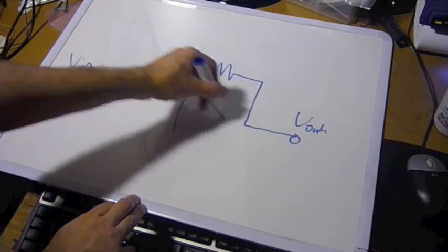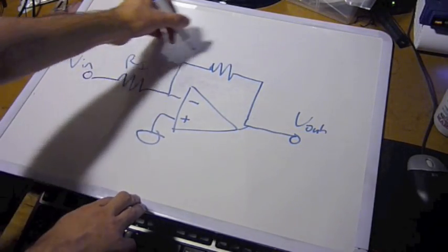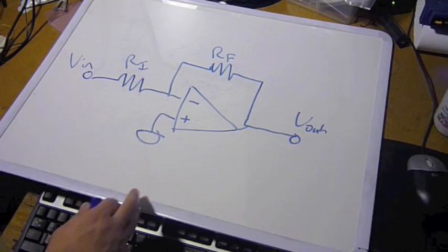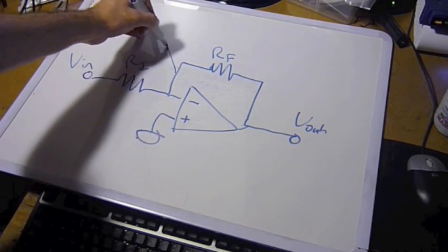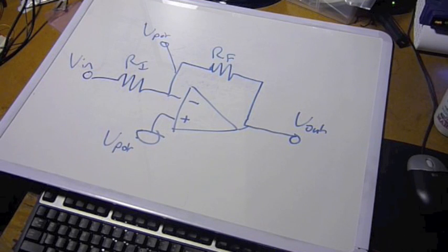For now, forget everything I just said. Let's do a little bit of math. Now, the first thing to remember is that the op amp is going to want to make the difference between the input terminals zero. Since this is an ideal op amp, we'll pretend this happens immediately and without any of the problems mentioned before. Now, if we set the non-inverting terminal to a particular potential, the 0-volt difference means that, well, when the op amp is settled, the inverting terminal will also be at that potential.